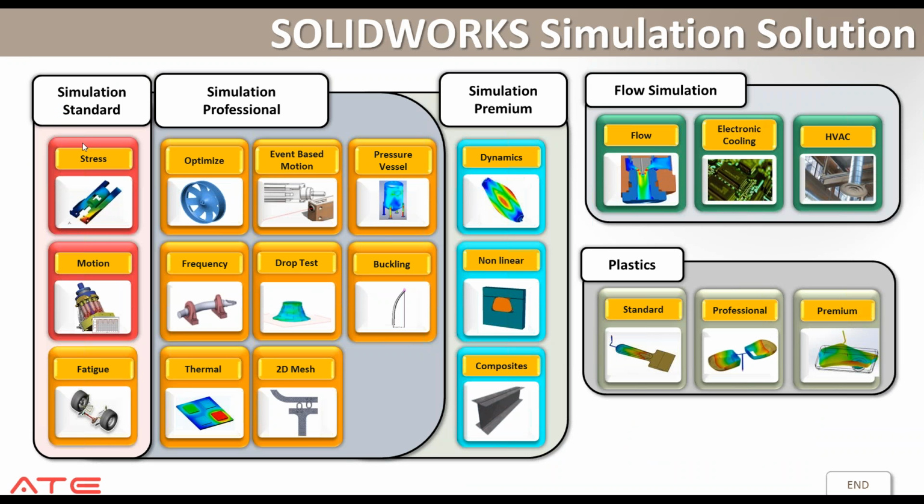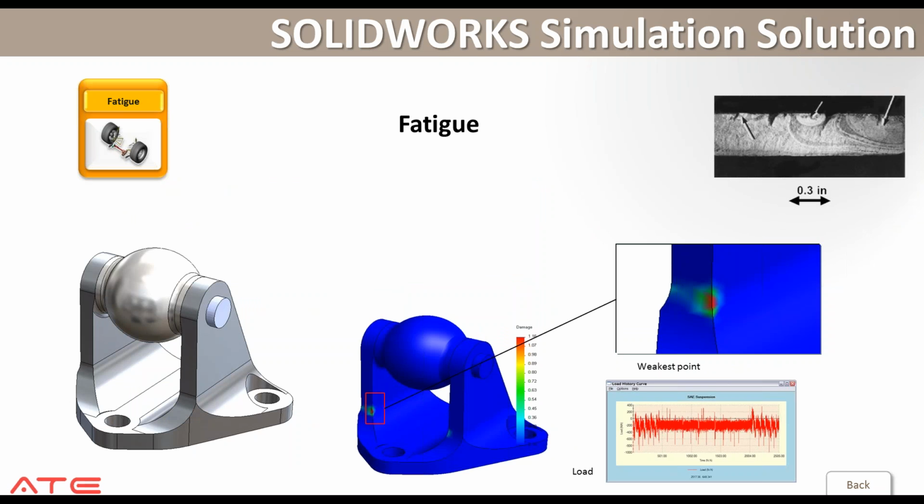So moving forward, under the standard packages, there is a fatigue analysis as well. Fatigue analysis, in other terms, is a cyclic load or cyclic test, which is repetitive loads on one component, and we calculate for the lifespan, or the factor of safety, the life and the damage on the components after a specific number of cycles.